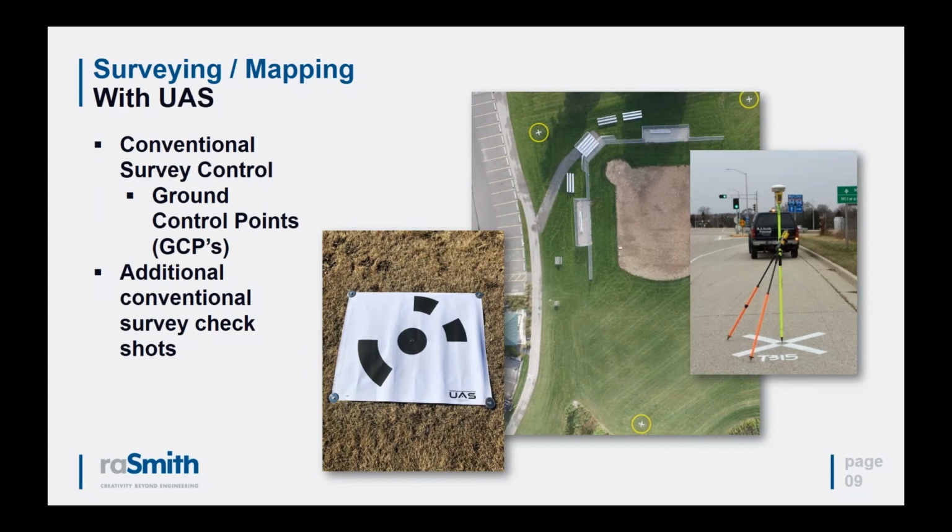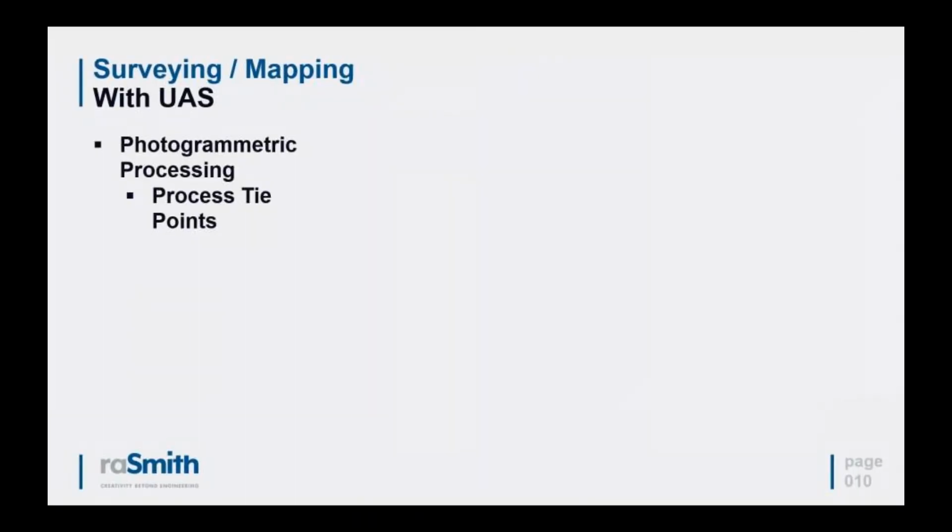I'll spare you all the details, but ultimately we take multiple GPS observations on that particular point, and then we average all of those to mitigate some of the inaccuracies that come along with GPS control. But ultimately, you end up feeding those XYZs that you've collected with those survey instruments into that photogrammetric process on the backside to essentially give your project scale, and also give you the ability to check those accuracies as well, which is really important from a mapping side.